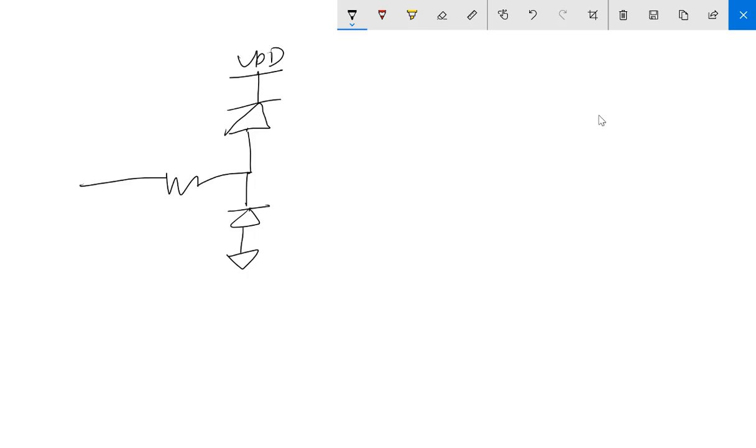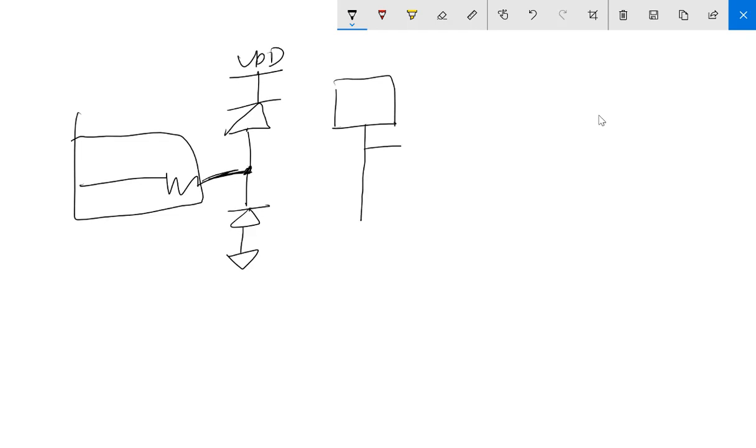So because this is being shorted to this terminal, it's like our pad, right? So that's a pad, and it has a metal two wire that comes out from it, right? And then you have a diode like this, another diode like this, and you have another pin here to connect to whatever is inside the chip.